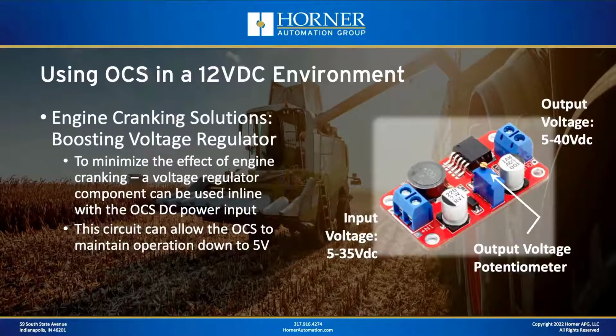Well, first of all, in a lot of applications, this is not a problem. Okay, it's not uncommon during the start of a machine that's engine related for the expectation to be that the OCS is either not on to begin with, or if it resets, it's okay. So it may not even be a problem that we need to solve. But if it is a problem that you want to solve, a component that we can use to do that is something called a boosting voltage regulator.